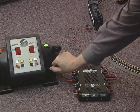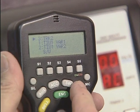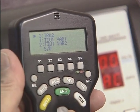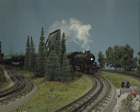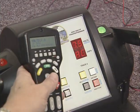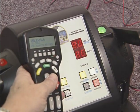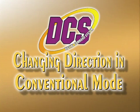After you have the TIU properly connected, power up the transformer. Choose the track you want to run by pressing the TRK or track button on the DCS remote. Operate your engine according to its conventional mode operating instructions, using the DCS remote's thumb wheel instead of the transformer to adjust the locomotive's speed. To change the locomotive's direction, firmly press and release the direction button.